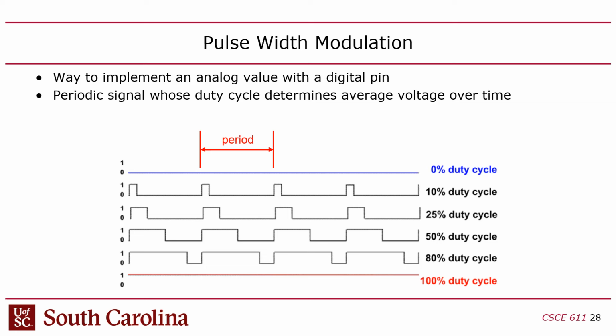Now, if you get into power electronics and you start getting into these solid state power electronics devices, like transistors, MOSFETs, but they put them in silicon carbide or gallium nitride semiconductor material, and or IGBTs, which is kind of the earlier technology, a kind of a hybrid between a MOSFET and a bipolar transistor. Those ones, depending on how aggressive your power electronic technology is, usually the more aggressive ones require higher switching frequencies. And usually that means you're going higher voltage with the power electronics. Higher voltage means higher frequency. So if you go to a Tesla, for instance, and you look at the power electronics in a Tesla, you're going to see a lot of PWM things in there, and they're generally going to run at possibly up around megahertz, right? Because they're higher frequency. But the frequency is a little bit more nebulous, how you pick that.